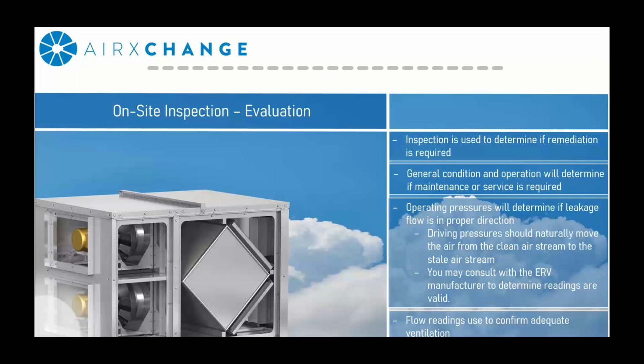Once again, and I can't stress this enough, the pressure gradient should be from the supply side, the ventilation side of the airstream, over to the exhaust airstream. It actually should gravitate towards that. If after inspecting the unit you find different results, you may want to consult with the ERV manufacturer or design engineer to determine the validity of the reading, and what could be done to adjust the operating pressures.